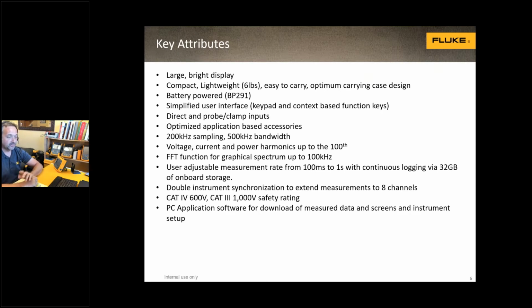So you can use any of our Fluke i-labeled clamps, or other manufacturers' clamps. It's a voltage input, so it's just a regular BNC connection. You can use quite a range of clamps with it and then scale the clamps. There's a setting internally to adjust custom scaling for the current clamps you're using, whether they're Fluke or a different manufacturer.